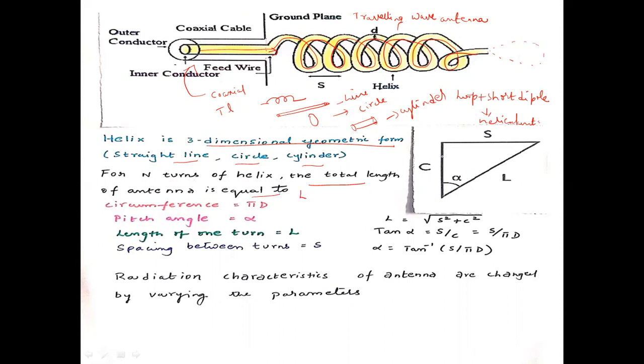So here I am going to analyze this helical antenna with the help of a small geometric form. Let us take a right angle triangle form. Here you see the separation distance between the turnings. I have taken the center position of these two as reference, and the separation or spacing between these two is referred to as capital S, spacing between the helix.